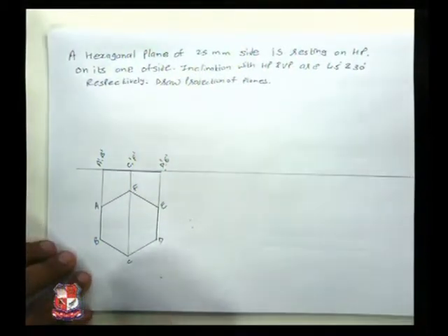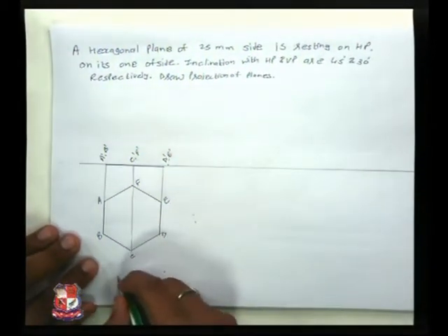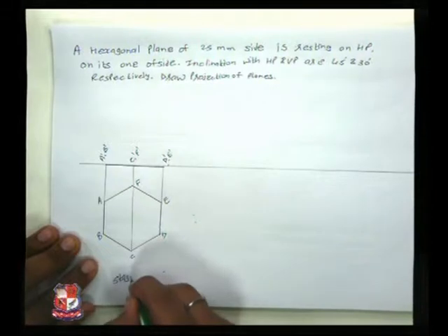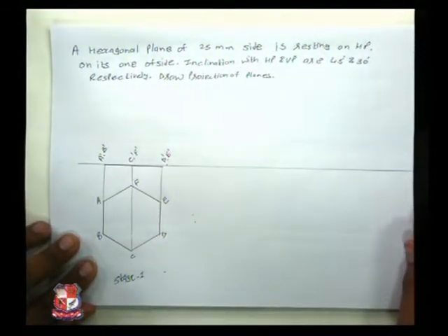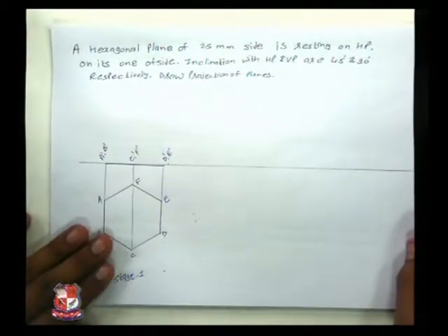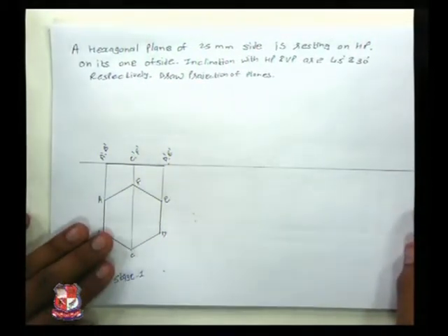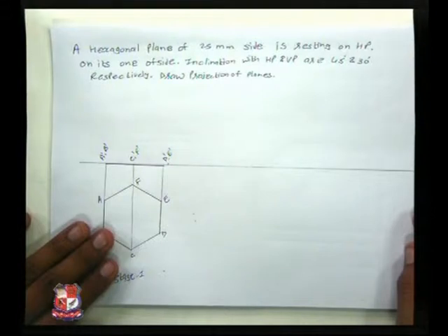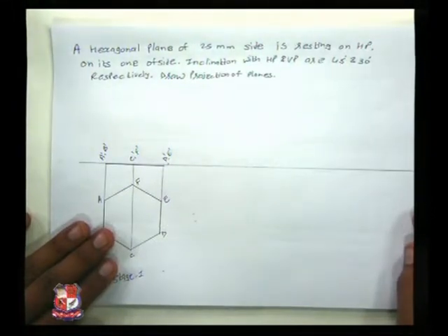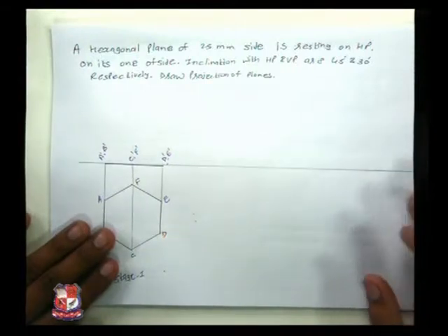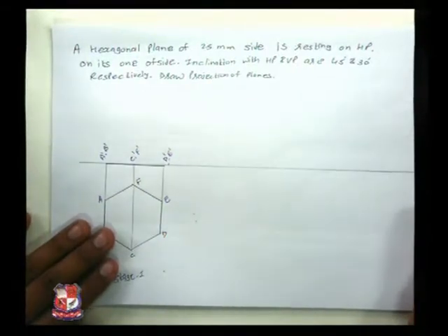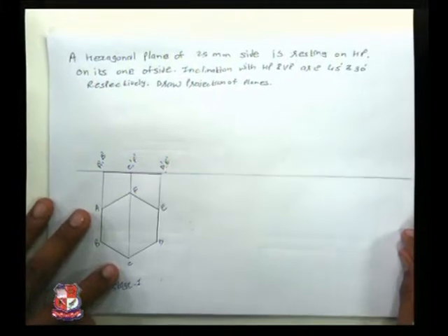The 3 projections. This is our stage 1, the initial position. If you remember these stages, stage 1 would always be the initial position, stage 2 would always be implementing the horizontal plane angle, and stage 3 incorporating the VP angle to the HP angle and the final object.